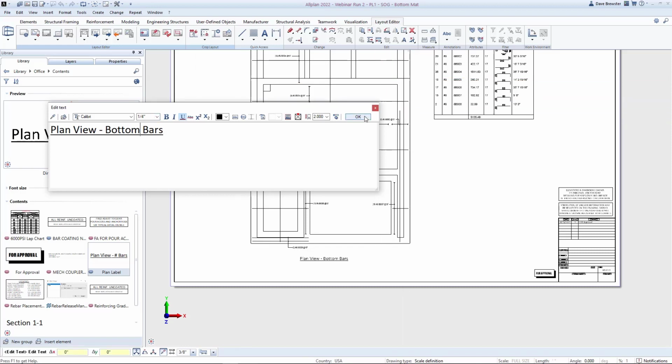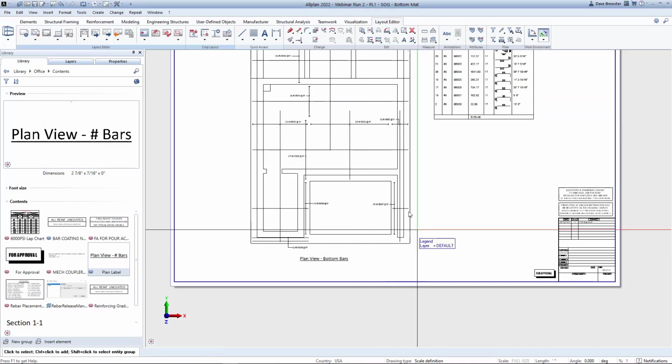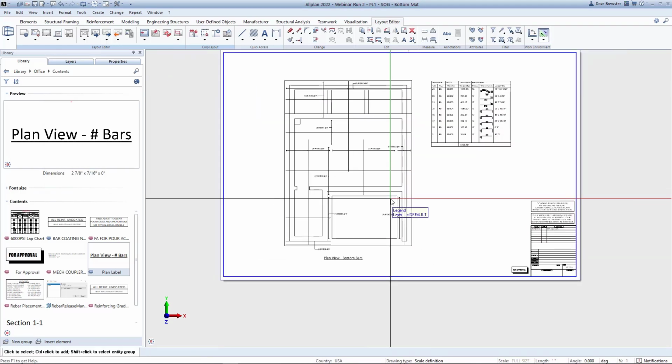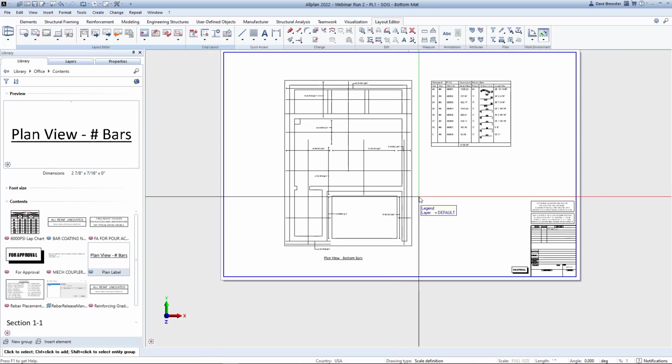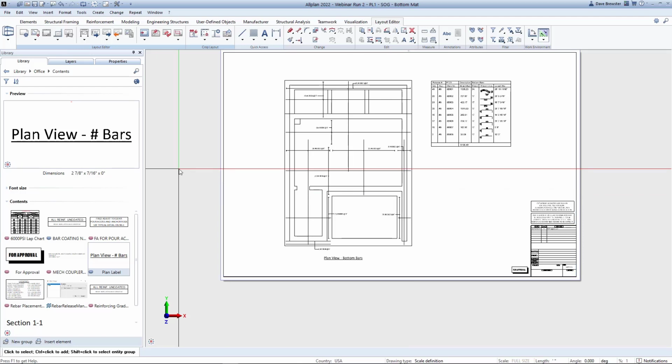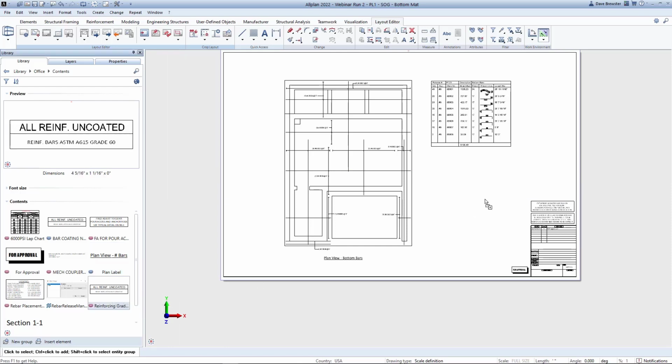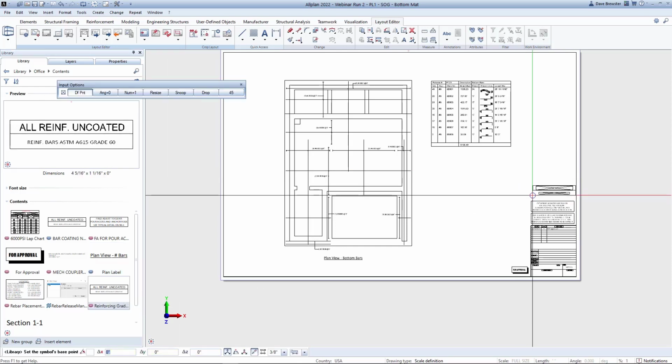So these are quick. This library file, you can host 1,000 different things, drag and drop them onto here. In the AutoCAD world, these are essentially blocks, but very quick access. You don't type anything in, just drag and drop and it's there. So I'm going to go ahead and drag and drop another little note here: reinforcing uncoded. So he's going to drop this note in here.